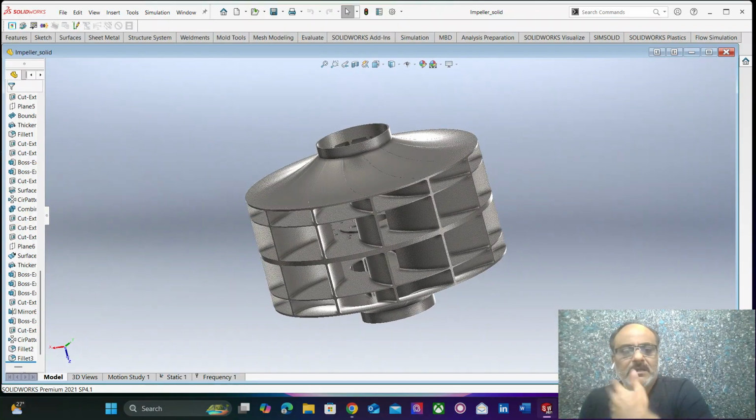So there are different formulations where we could go for isoparametric tetrahedrons, or we could go for brick elements, generally called hexahedrons, or we can also go for hybrid algorithms where we have most of the elements as hexahedrons, then we have pyramids, wedges, and tetrahedrons. So that is called a hybrid. Since this is our initial simulation, we go for automatic isoparametric tetrahedron elements.